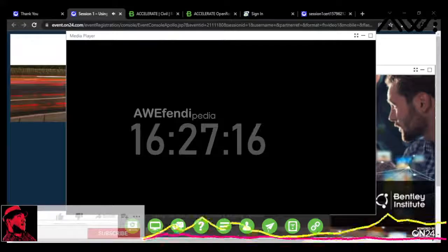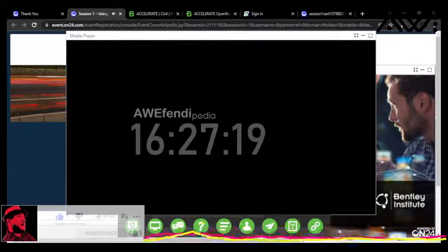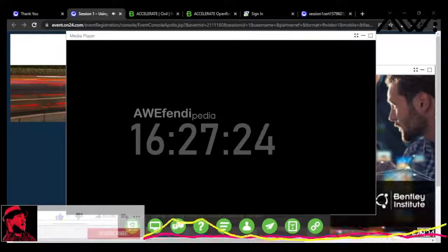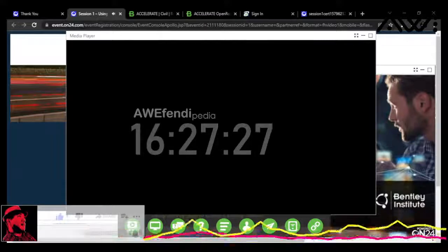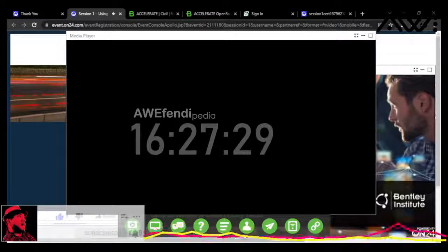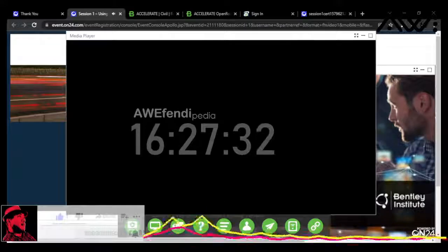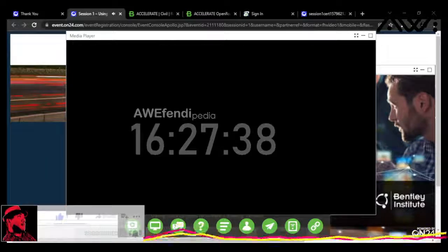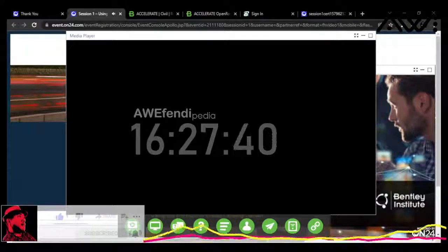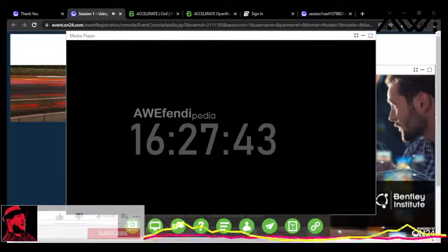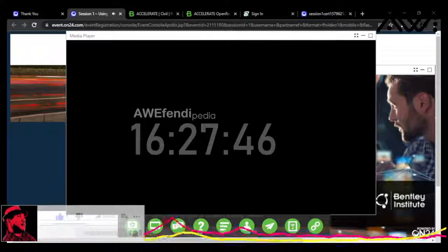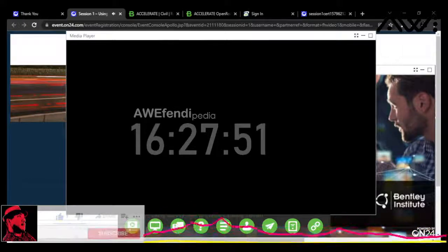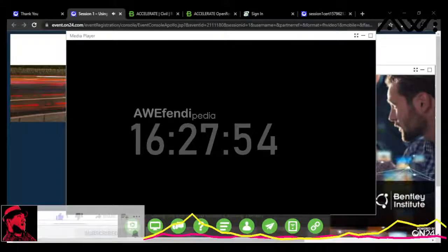Okay, so we fixed our driveway over to the west. It looks like we fixed up our stream, and our bridge deck's pretty good. I think our 2D graphics are pretty good now. I want to start looking at the terrain, at the 3D. And so what I'm going to do is click on the terrain, and change its feature definition real quick to get the triangles. So existing boundary is its current feature definition, sorry. And I'm going to change that to existing triangles.